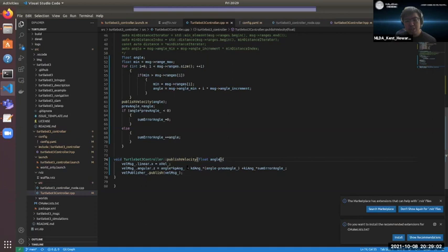You can also just use angle times KP angular and leave the rest to be 0 if you want to be lazy about it. This will probably leave a path where your robot moves forward in the wrong direction. And as the error gets bigger, it starts to turn faster.